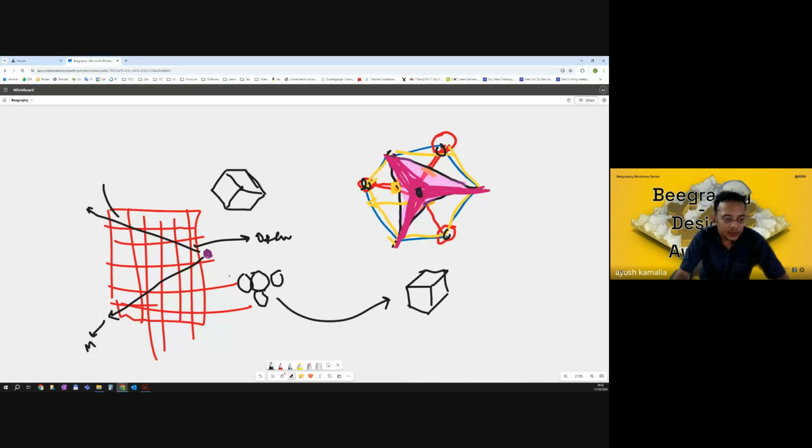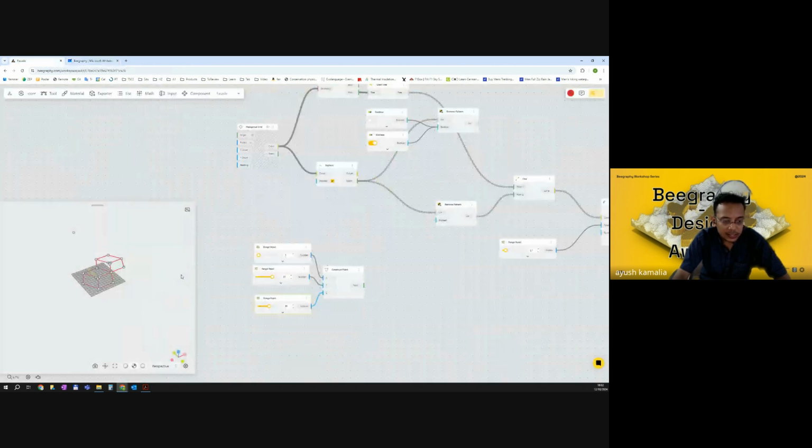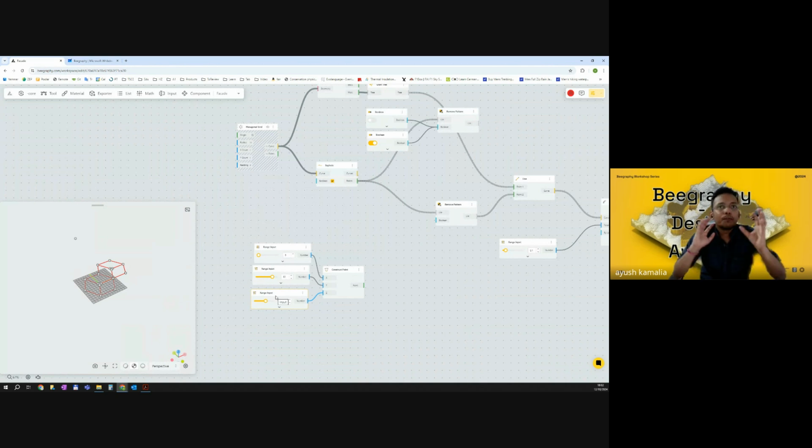What happens if we just move this point? So this attractor point will help us in parametrically control this. If I move the attractor point here, what happens then? This module will become the most open module, and the one which is the farthest, which is this one, will become the most closed module, and everything in between again will follow the progression. The good part is once we are done with the script, we can easily change the location of this point through these 3 sliders, and the whole pattern across the facade will change.